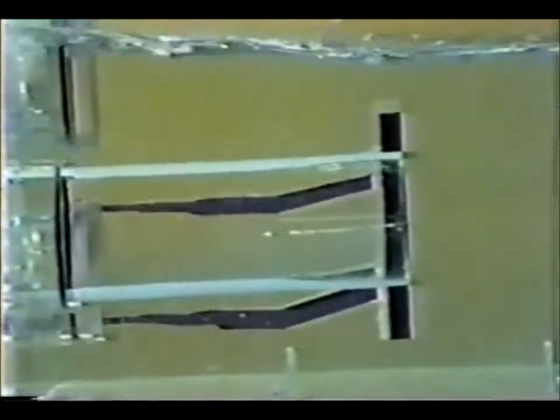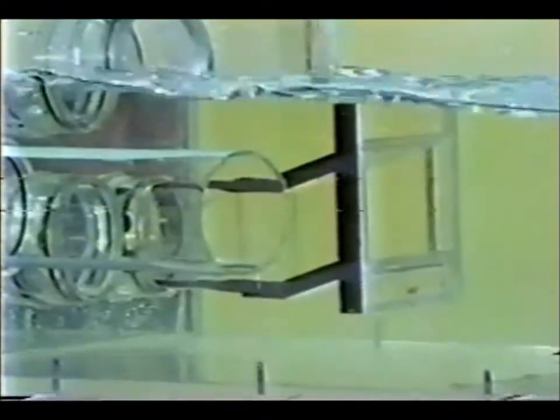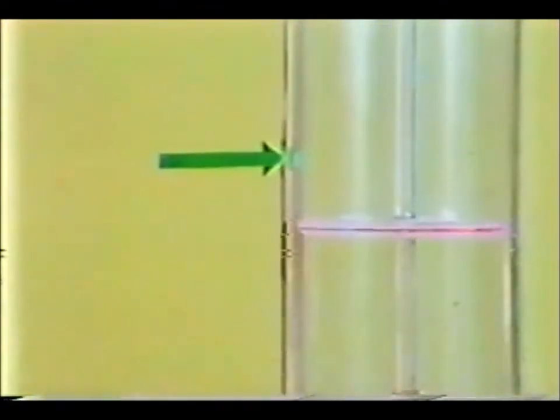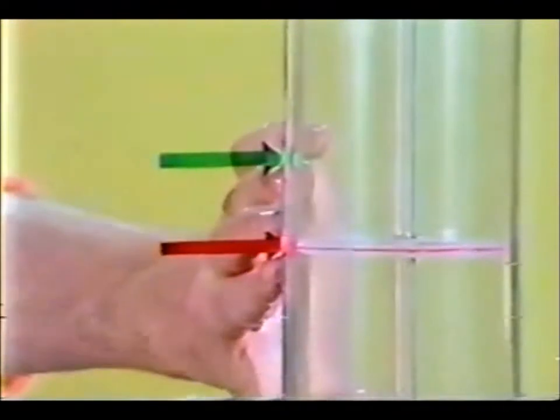The outlets and inlets of the two culverts are at the same elevation, but the throat for the slope-tapered entrance is 1 inch lower than the throat of the side-tapered entrance. The difference in the headwater pool levels also is about 1 inch, with the slope-tapered inlet having the lower headwater. The 1 inch represents the amount of fall at the entrance of this slope-tapered culvert. If the fall had been 2 inches, then the headwater pool difference would be 2 inches.